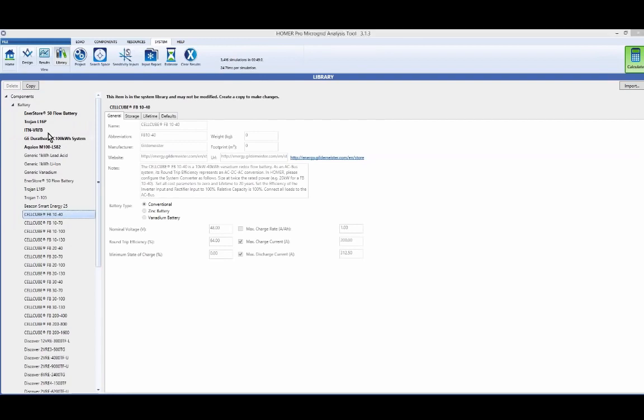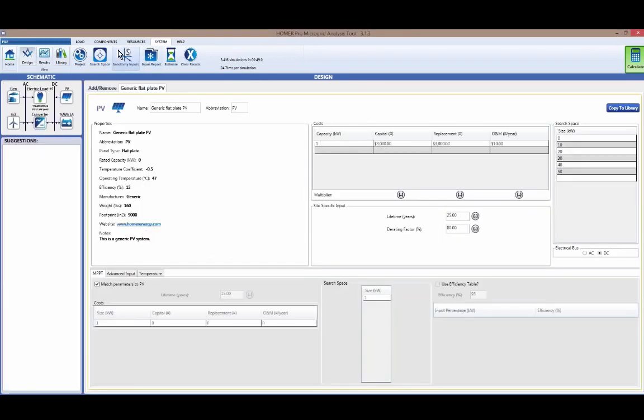And let's see, let's go back to our design. Let's point out some of the other components that might be of interest. We now have a thermal load controller. So a thermal load controller allows you to manage excess electrical loads and contribute to the thermal load in a combined heat and power system. This is a new feature in our combined heat and power system analysis. You may know these thermal loads also as dump loads or secondary load controllers. And we also have hydrokinetic turbines. And this is a technology that allows you to use momentum of moving water to generate electricity.